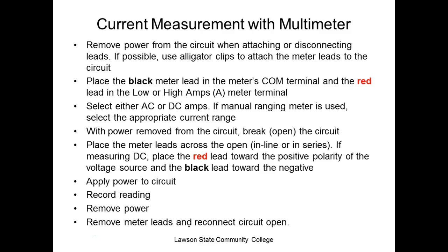Ammeters have almost no resistance at all. So if you put it across something, you've got a short. Everybody understand that? Hopefully it'll blow the fuse in your meter, but it could create a spark, which could be bad, right? Apply power to the circuit, record the reading, remove power, remove the meter.